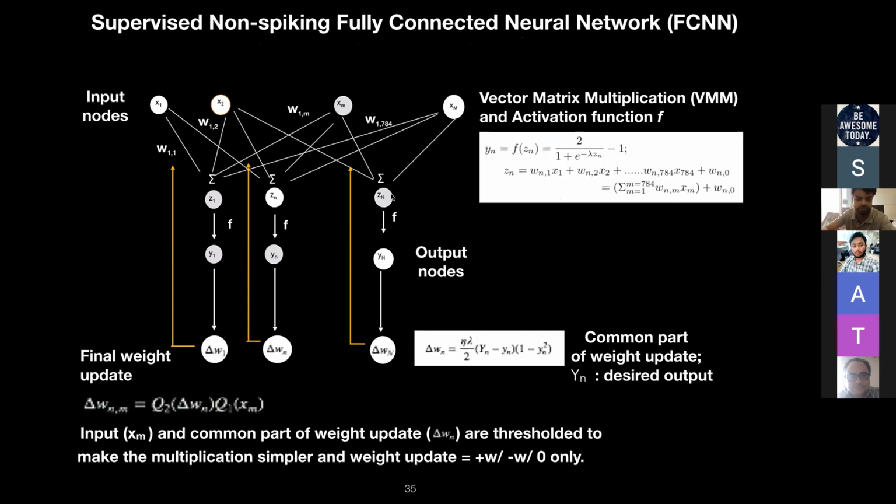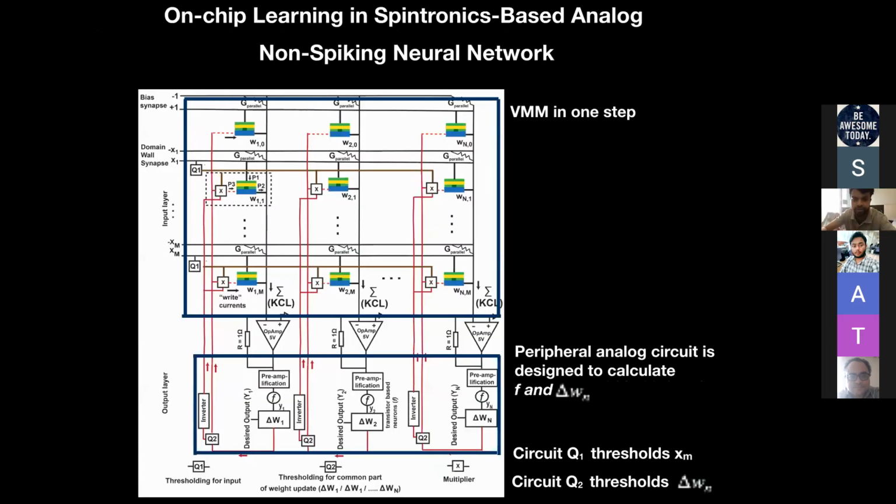No, sir. Okay. So now you see the weights multiplied by the input, then you apply a nonlinear activation function, then you calculate the error, and based on the error, you feed the weight changes to the synaptic matrices and the weight values update, right? So what we do is we model these domain-wall synapses on micromagnetics, and we get this conductance versus current pulse property that we had shown you before. Now we convert that into some kind of Verilog-A model, and we place these Verilog-A models in the SPICE simulator on Cadence Virtuoso, and then we run this simulation.